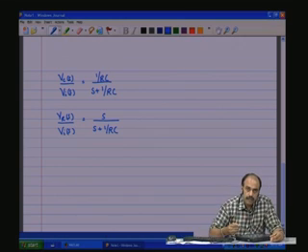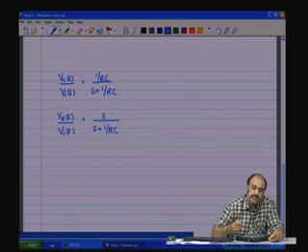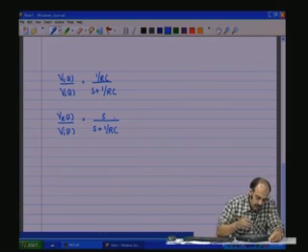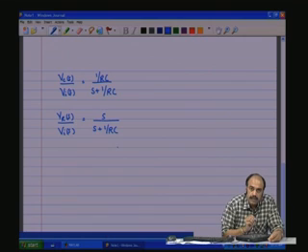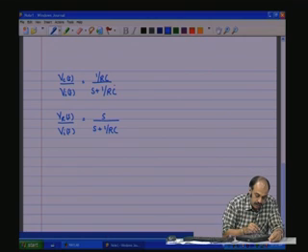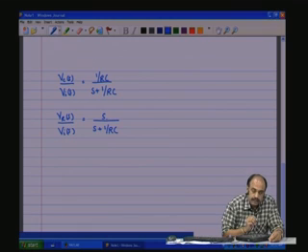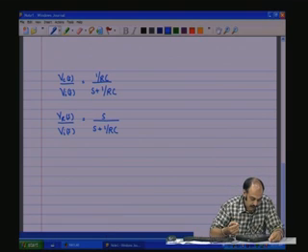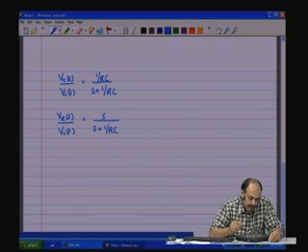This output variable Vc is across the capacitance with respect to the input, and the other is the voltage across the resistance with respect to the input. Now, here if you see, the poles are the same, they have the same pole locations, only in this case there is no 0, and there is a 0 here in this case, a 0 at S equal to 0. How do they affect the responses? We will shortly have a look at it in the MATLAB.